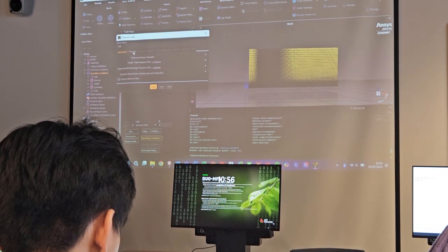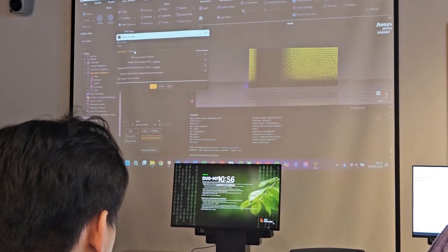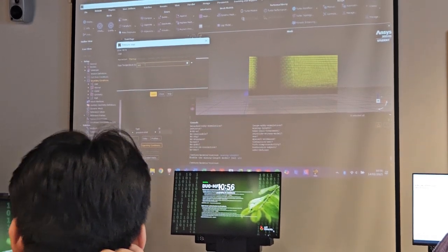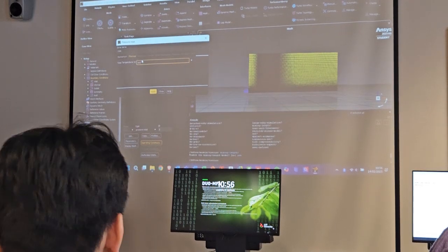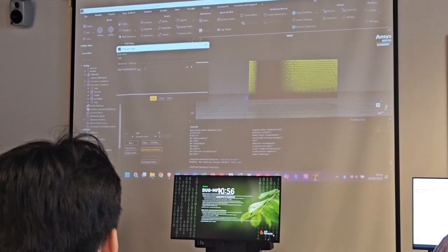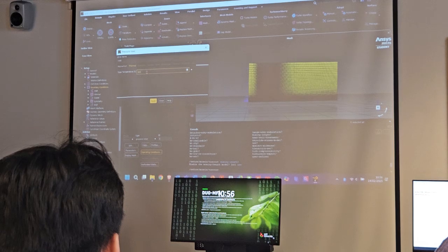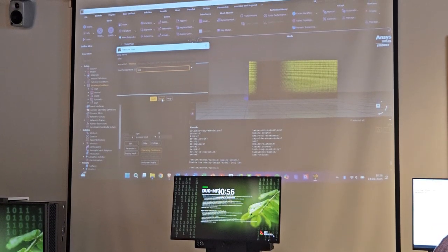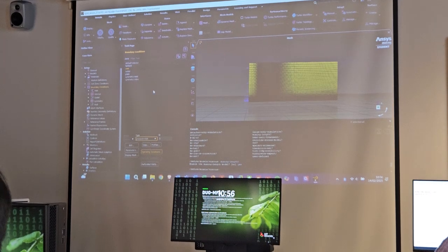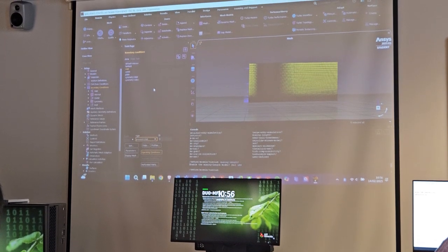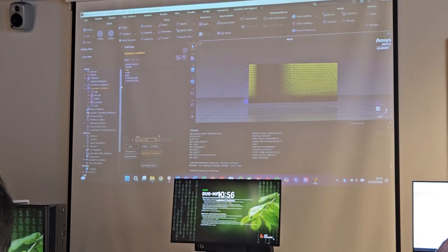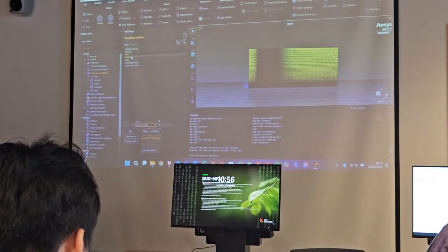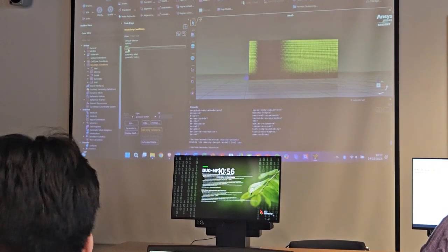Then in the thermal tab over here on the top, we can also change the total temperature. We said total temperature 300 Kelvin. This is the one already here by default, so we don't need to change it, and we can close this. So now we set the inlet, and we need to do it for the next one.